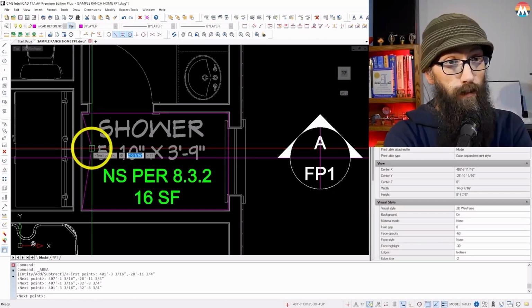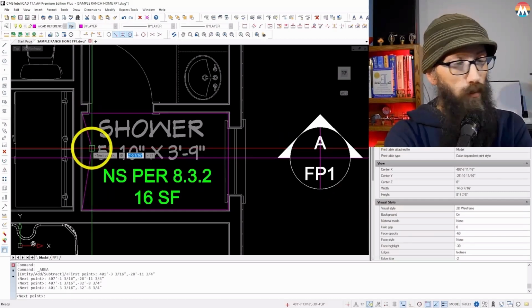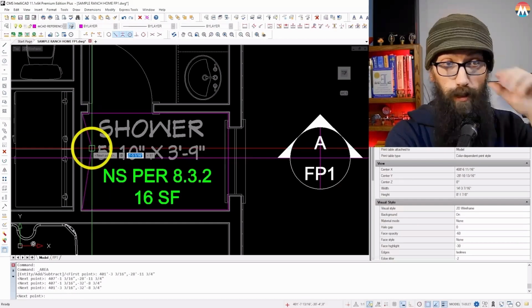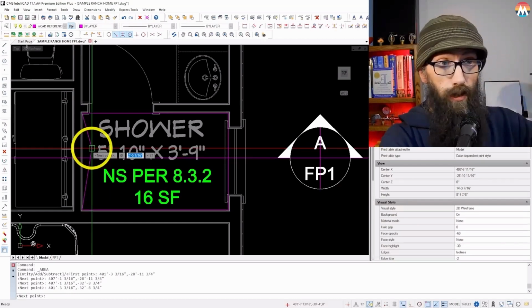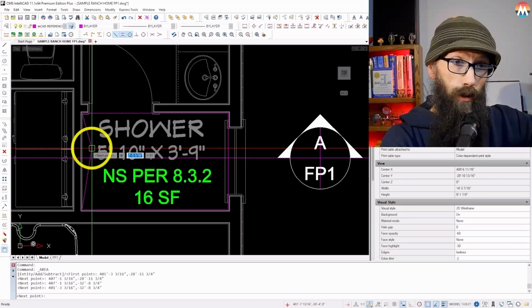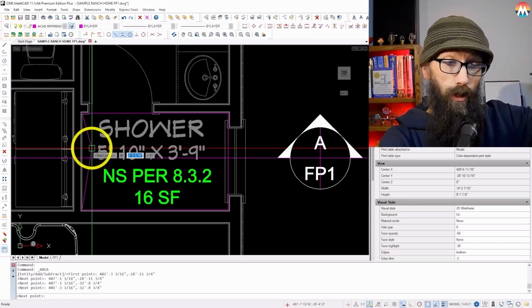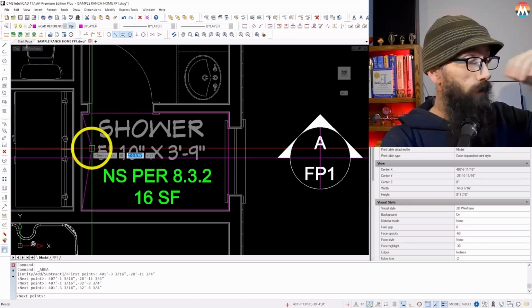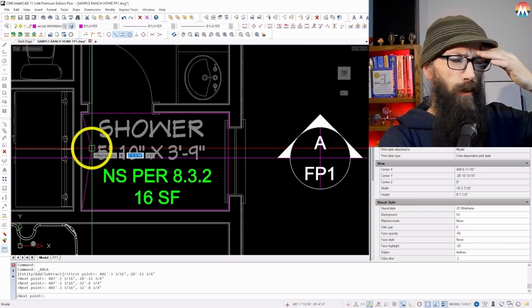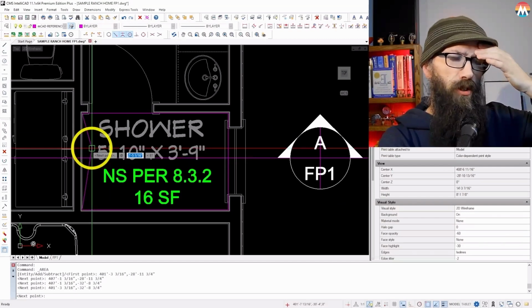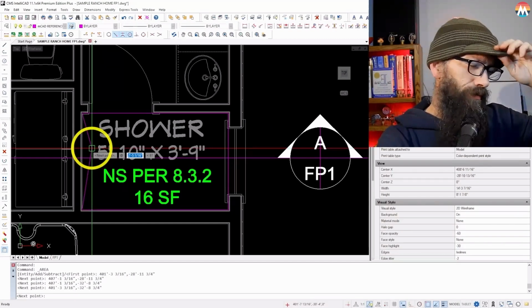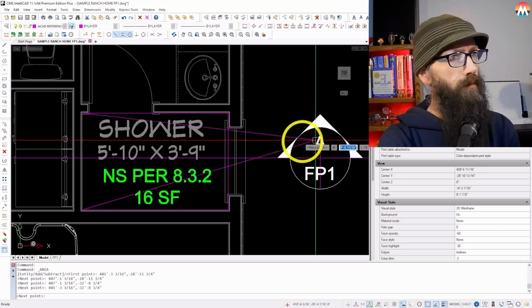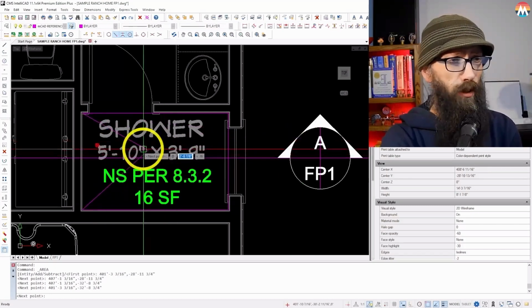It just needs to have a lintel, which NFPA 13D has a definition of. It's basically like a header over a door. You have to have a piece coming down from the ceiling that I want to say it has to come down, I think it's 12 inches, but I'm not sure. And you can basically treat that like a wall.